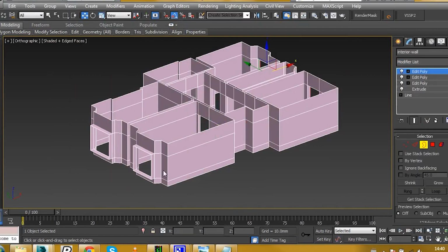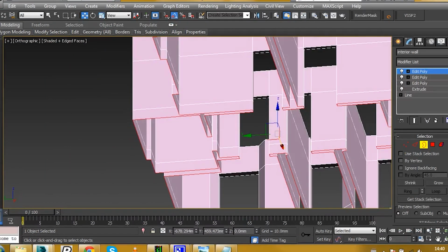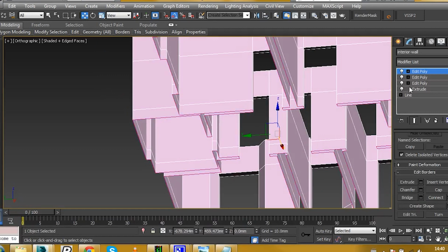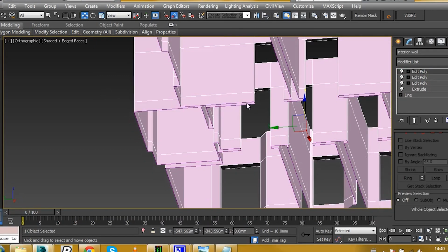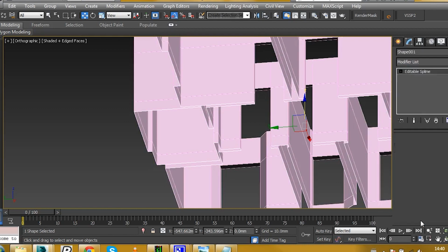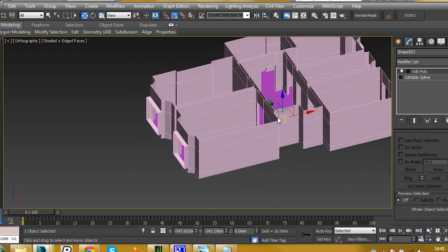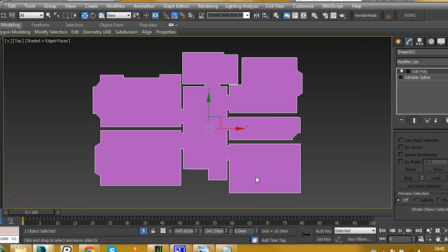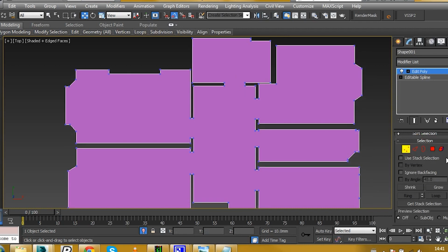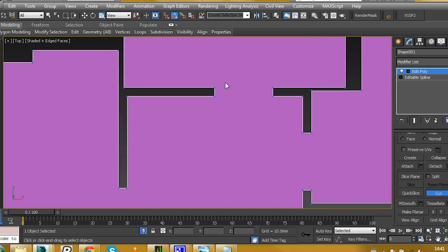And under selection, select border. If you select the very bottom and scroll down in your edit poly menu and select create shape, deselect your edit poly. If you select the shape you've just created and under modifiers apply an edit poly to this, you can see we've created a floor for the full object. If you isolate this floor, go to your top viewport and under selection select vertex and edit poly. We can select cut and we can detach areas of floor.